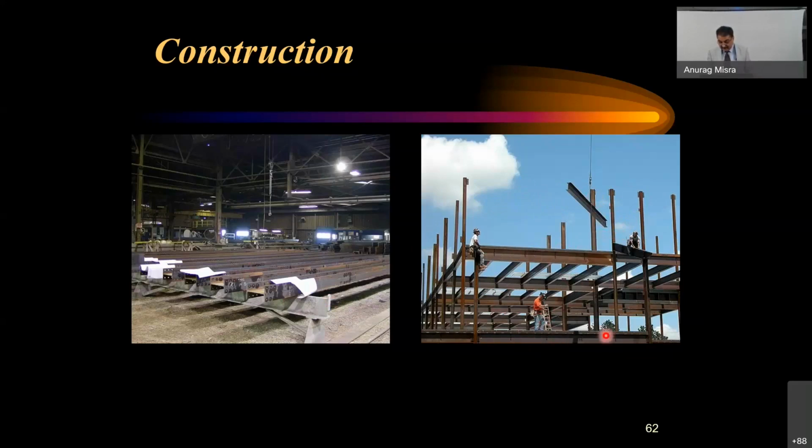So I think this, even the ground, the lower floor is not cast. Your next floor is getting ready, and immediately the construction starts here. So many times it happens that you are at the third or fourth story, and on the first floor, the casting of the slab is going on. And the moment you go up, the finishing also starts.